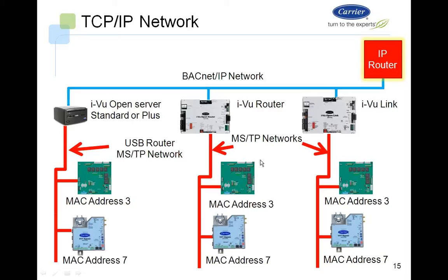Since these MSTP networks are all unique, the fact that the MAC addresses are identical is of no consequence because they are separated from each other using these MSTP to IP routers.